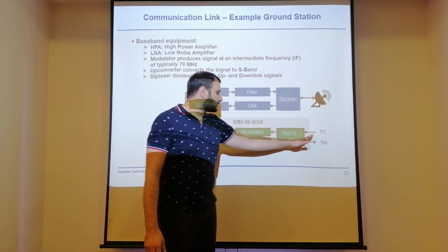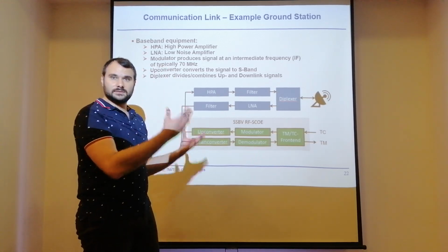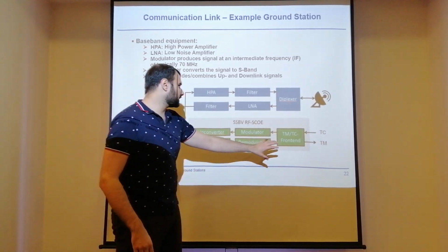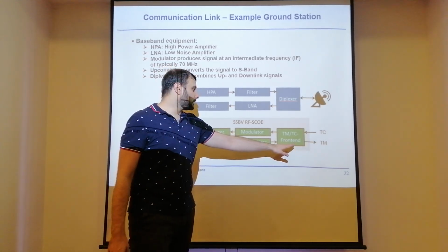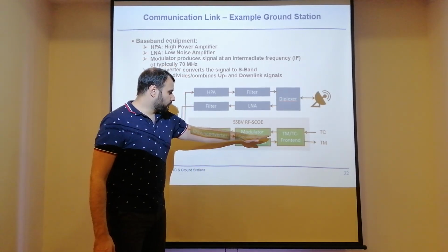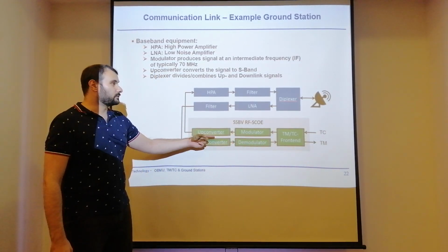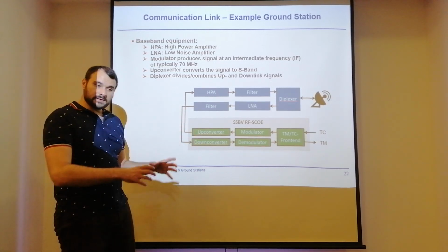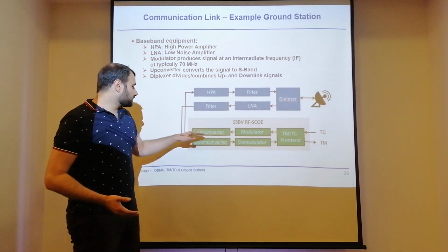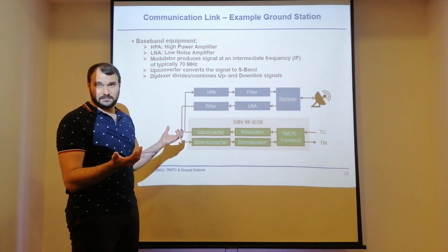You introduce your telecommand into your TMTC front end, so you can do the checkout. The TMTC front end will do maybe the forward error correction, the encoding. Then you do the modulation of the data, and you convert it to the frequency where you need it. The output of this unit is already the signal you want to have at the satellite.